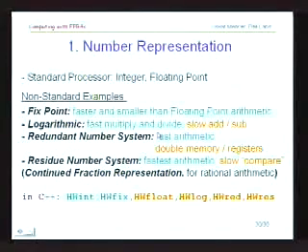Now, looking at the details here, let's say in the previous case we had just hardware integers, but we could as well have a hardware fixed-point variable. We could have a hardware log variable or type. We could have a redundant variable type. We could have residue numbers. And these are all fairly standard arithmetic methods that people use in order to design VLSI chips.